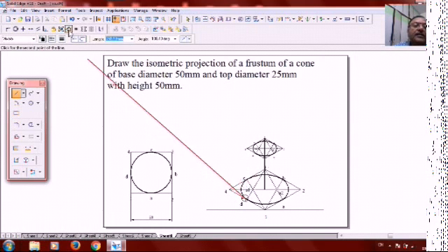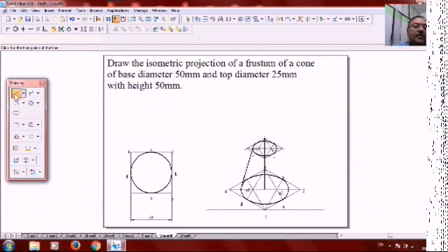Once you click this and select the line afterwards, this symbol will come, or automatically when there is a curve it will come. That is a tangent. Similarly, do the same thing for the other portion also. Click anywhere. No, it's not taking tangent. It must give a circle. Yeah, that is the tangent symbol, and then click it here. It will be a tangent.